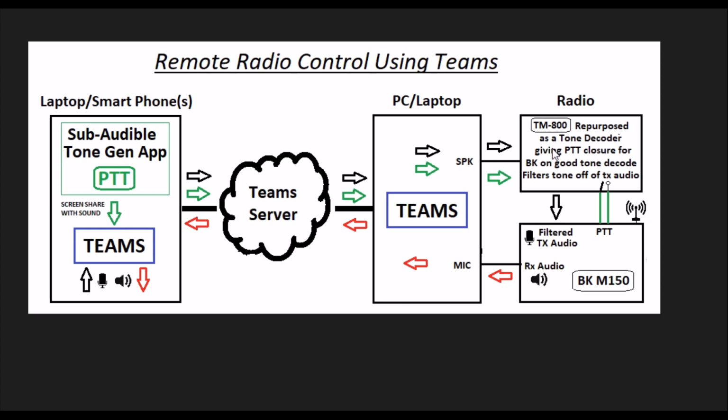Also, any shared tone repeater panel, or community repeater panel, would do the same function. But really, any old radio that's got a good working audio section that can do a PL decode is all you need. So if you've got an old junk radio laying around with a busted power amplifier or some other oddity, but the logic of it works and it can still decode PL, you can repurpose it for this application.